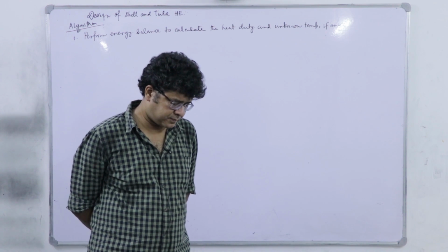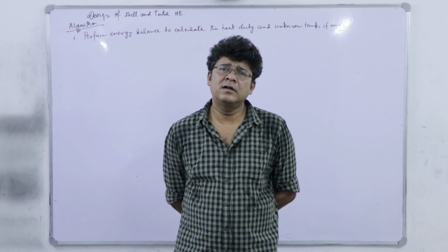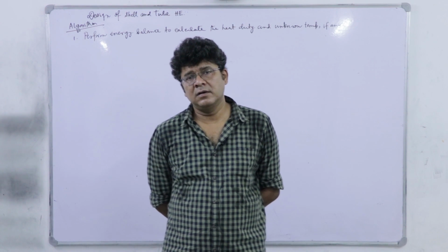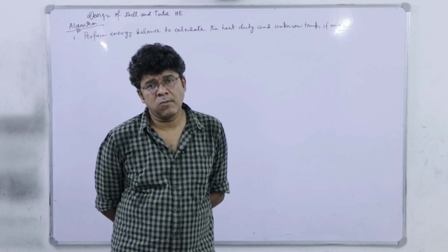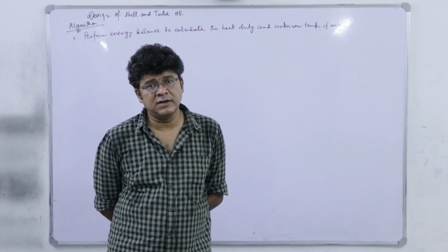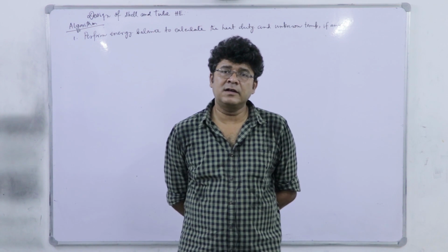And the outlet temperature we consider to be the same as the inlet to the respective plant's cooling tower. The water inlet temperature of the cooling tower must be the outlet temperature of all heat loads. So, from there we can get the inlet and outlet temperature.